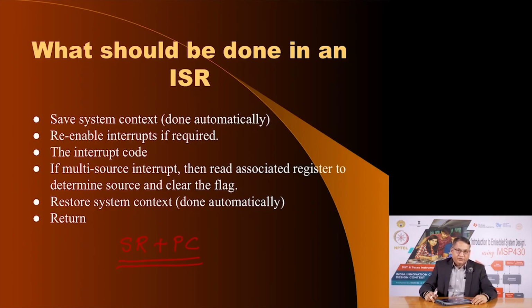Now, once you enter an interrupt subroutine, the global interrupt enable bit is turned off, which means no interrupts can happen during the execution of this program. But you, as a programmer and a designer, are free to enable the interrupts, which is what we are saying here. It is possible to enable interrupts within the interrupt subroutine, and I would advise you to exercise great caution in trying to re-enable interrupts within the interrupt subroutine. Of course, after that would come the actual program that you would execute in the subroutine.